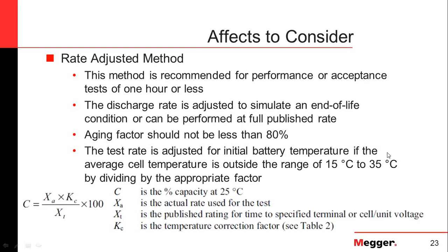The only other time you adjust the rate of current is if the temperature range is outside of 15 degrees Celsius to 35 degrees Celsius. As long as it's within there, you don't do anything else with the test current rate.